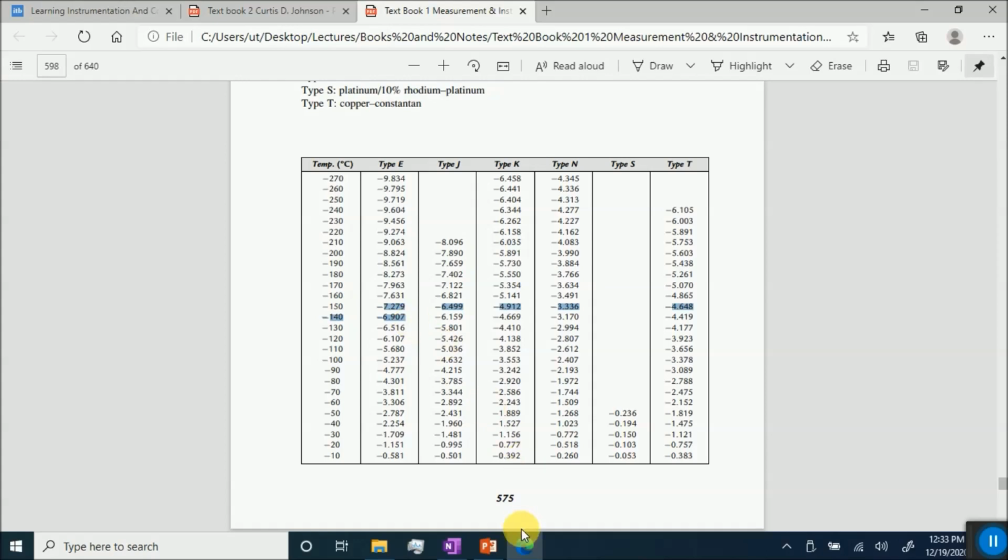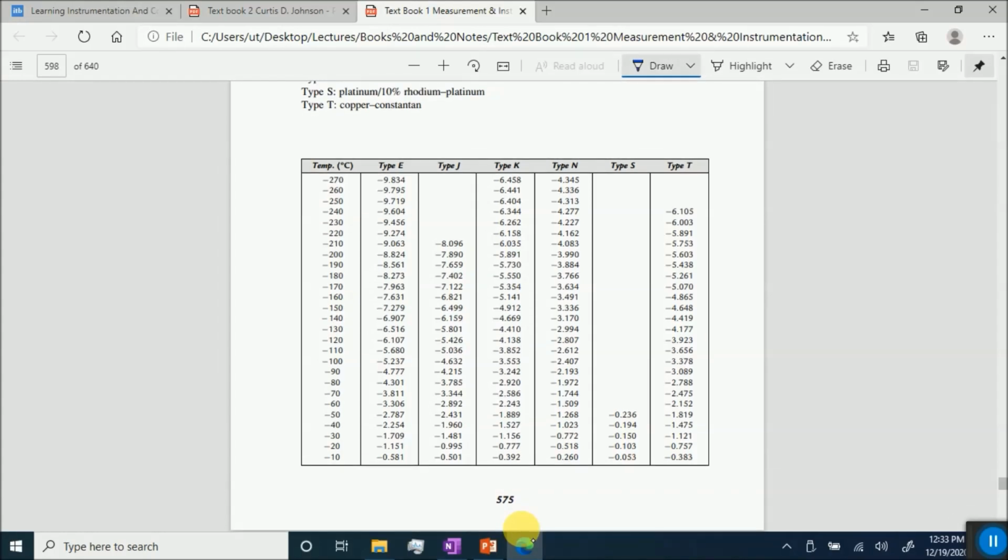So you just connect those 2 points like here. This is one temperature, this is the second temperature, and here is some EMF produced. So you just interpolate it, and you can find out what the value of EMF produced would be at this point. So that is a fairly simple mathematical task.